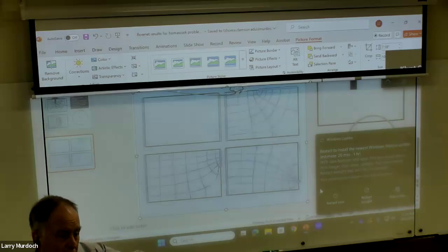Along the stream tube, the ratio has to stay the same. So if that's going to happen as the streamlines converge, the equipotentials are going to get closer together. Okay? It's a big deal because the streamlines will converge on wells, and wells are coming up in the class. We're going to spend a big chunk of time on wells.